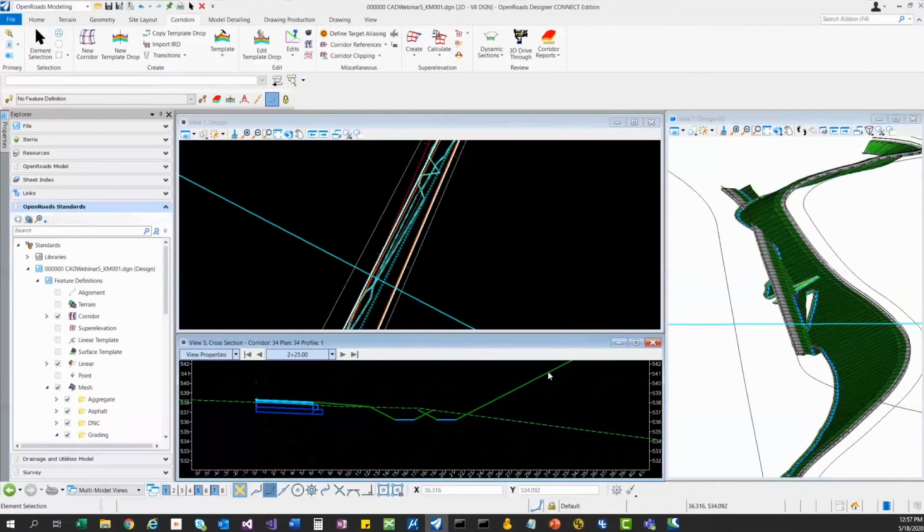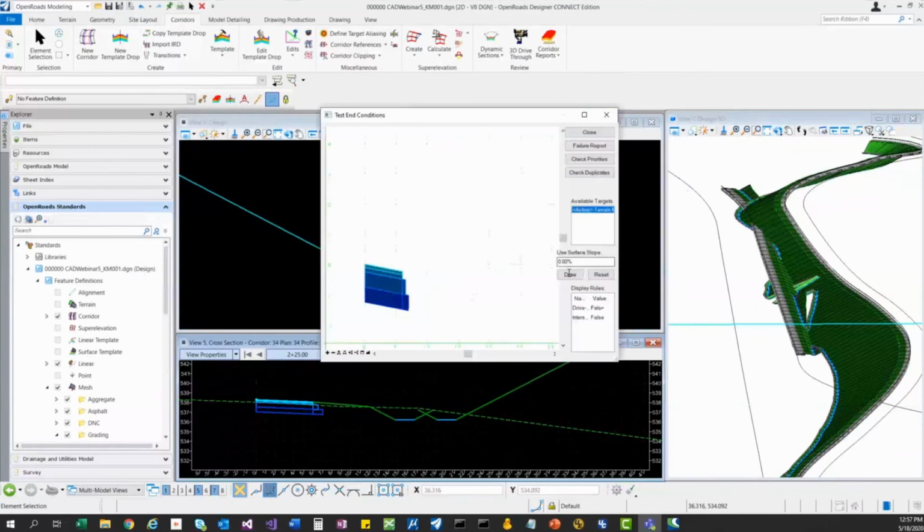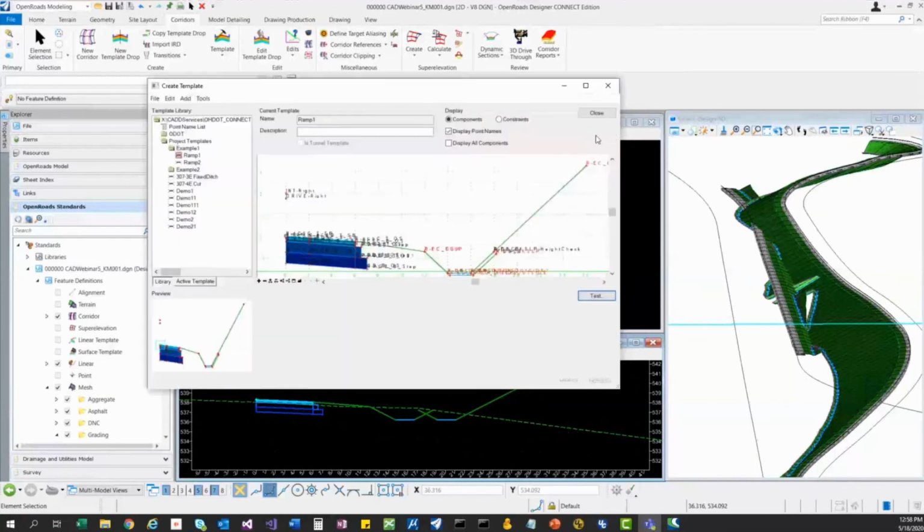So those fixed ditch templates kind of force a ditch in. What I'm talking about is these templates right here. We're forcing a ditch, and this is all great when you're in this kind of condition. But as your surface gets lower, in order to actually get a ditch to draw in, you're going to need to push that ditch down lower. That's what these templates are doing, forcing that ditch to be placed here. So we're going to use this as a way to help us out in this situation, okay?